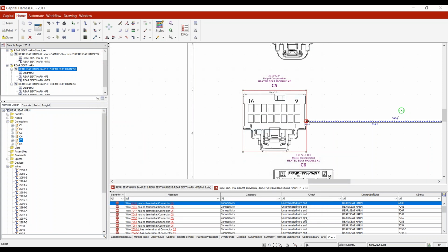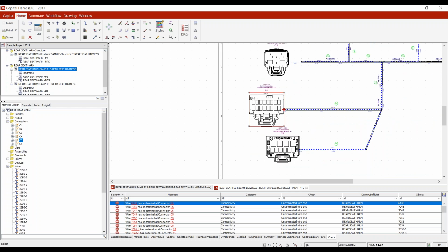So then we need to change the wires that fit the terminal inside of the library. In retrospect, if that's not the case and you just don't have that terminal in your library, then this just means that you'll need to look for a terminal that does fit that wire, and it'll be a new purchase for your organization. So it'll be a new terminal that needs to be used.